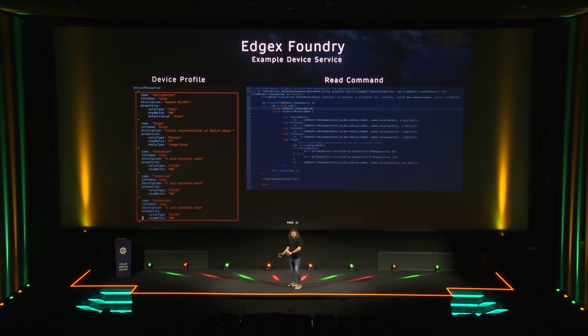So in order to bring a hardware device into EdgeX, all you really have to do is define a device profile, which is just a YAML file describing the data types that your device reports and whether they're read and write or read only, etc. And then implement this pretty simple interface using their SDK around your device driver.